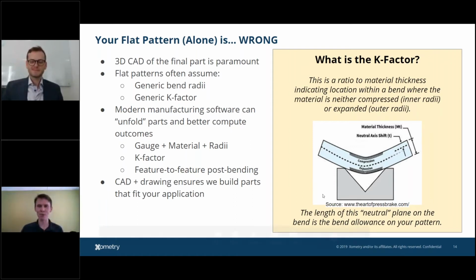So this is all moving into designing. So Callye, I'm going to bring you in along the way here. But when we're designing for sheet metal, there's going to be some best practices and rules to go by. Sure. And again, this all has to do with the actual process. I'm working with a flat sheet. I'm using tools that have certain advantages and disadvantages to them. So angular bends, for example, even cutting that blank out, creating that profile, all those tools are a little bit different. They all work together very well, but being mindful of those is going to give you the best results.